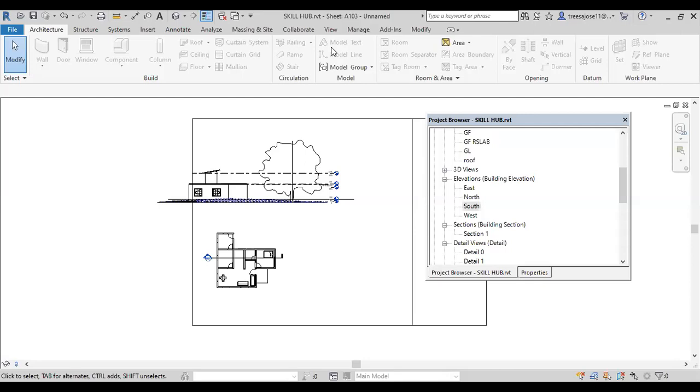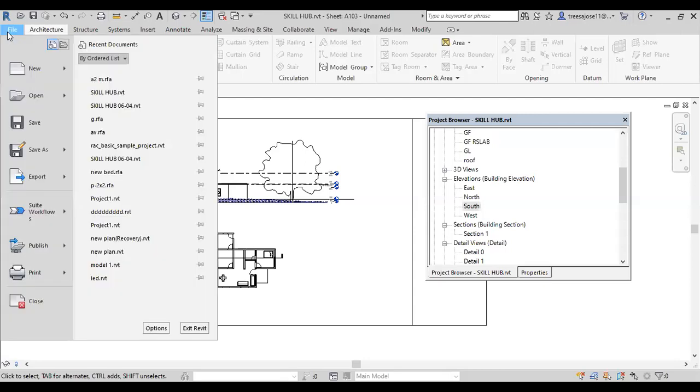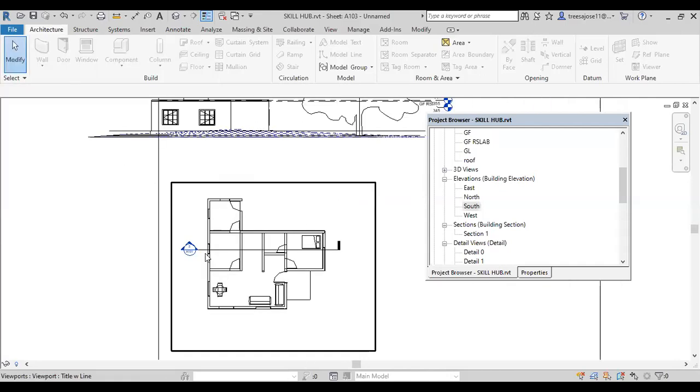Okay, the two simple steps we have to memorize while exporting. In the case of solids, you have to select the solid. Then for units, you have to select the current unit. If that is in centimeter, you set the unit as centimeter. Then only in AutoCAD will we get the wall as 23 centimeter. If you select mm, we will not get it correctly. Okay, this is how we are creating the drawing.